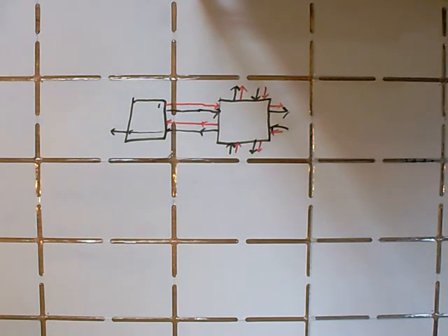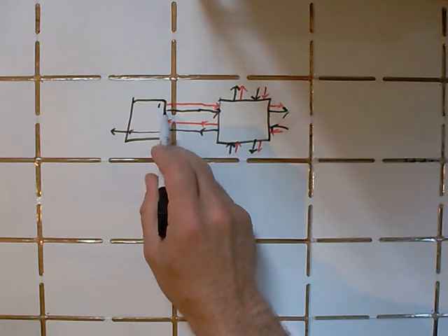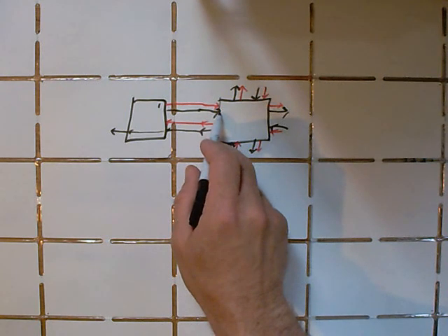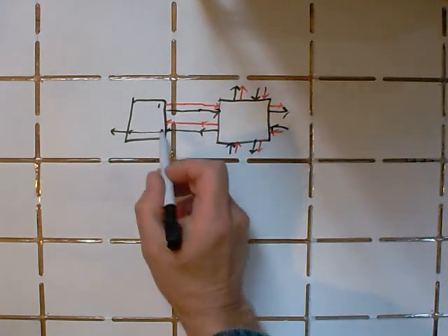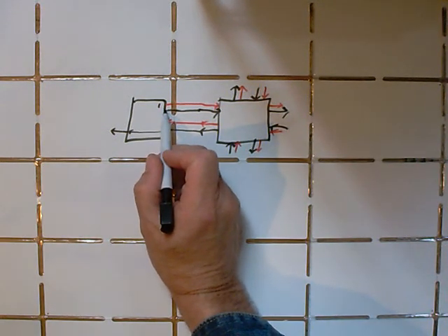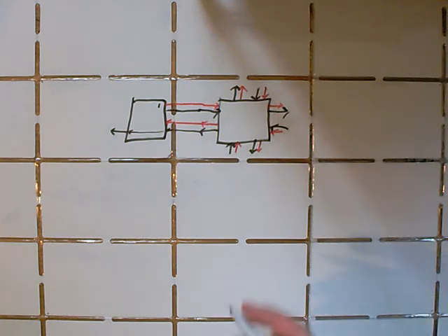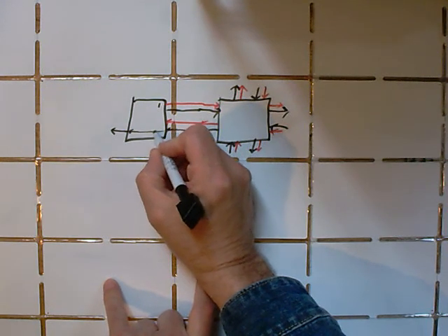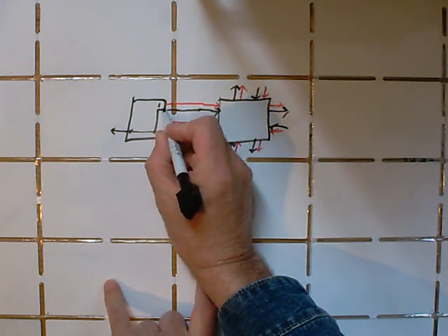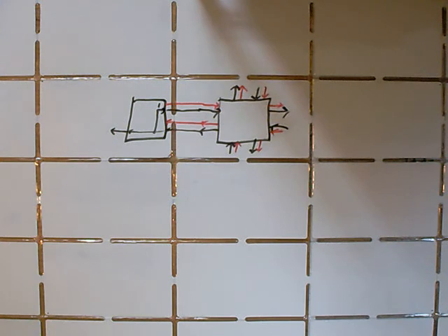This is a useful way to read a cell's contents, but the problem with it is that unless we put something meaningful on the D input of this cell, we're just filling up its truth table with zeros. In other words, it's a destructive read. Now, if we put a pattern of 1s and 0s on this D input, we could load the target cell's truth table with some sort of useful pattern. Well, a particularly useful pattern is simply a copy of the bit streams that we're reading out of that cell.